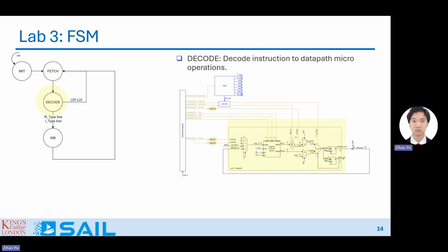And then is a decode state. Decode state is basically everything you covered in the previous single cycle CPU or multi-cycle CPU. It controls all the signals inside this CPU. However, the next stage is different because in the last task, we saw that the load instructions only need one cycle to complete, while the arithmetic execution requires 2 stages to complete. Therefore, for the load instructions, you can just go back to fetch after decode is finished.